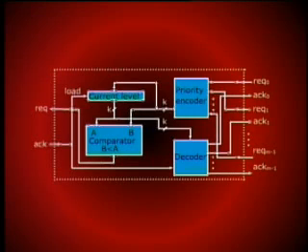This index is compared with the current level, and if it is smaller, an interrupt request is sent to the processor. When the processor acknowledges the request, the current level is set to the level of the new request, and as a result, an acknowledge is sent out on the daisy chain with acknowledge J.